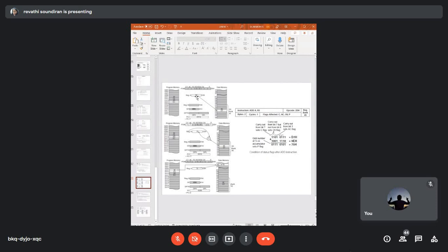And now you have to keep track of your program counter. So at this stage, your program counter is incremented by 1. So it goes to the next memory location for fetching, that is 01FD. So the next instruction is add. We are asking to add A comma R5. That instruction is going to be executed.